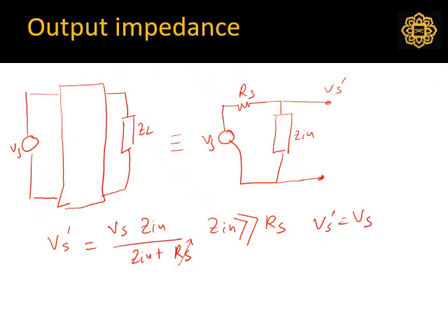In this case, your full voltage is brought into the system, across the actual load, if the system has an input impedance of high value, so that you can have a full voltage representation across the load. Input impedance should be high.